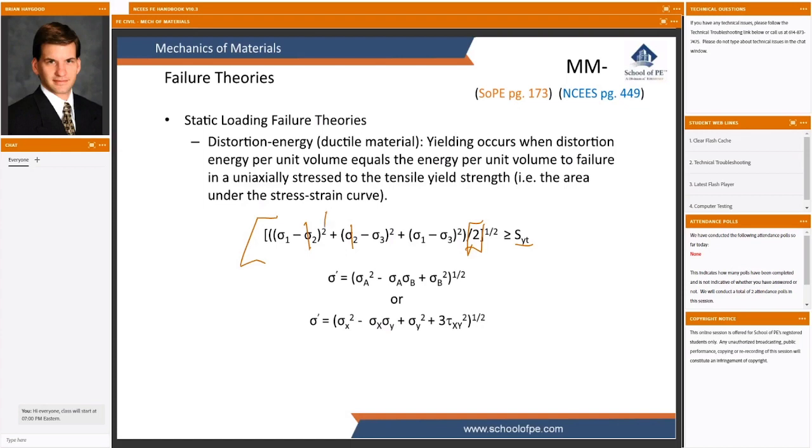So we're going to square these values, square these values, square these values, add them all up and take a square root, which means it doesn't really matter if something has a positive value or a negative value, except that you're comparing them here, so you do have to be a little careful with that. So this is one case in which we use a Pythagorean theorem, but we can't totally ignore the sign on everything. As usual, tension is positive, compression is negative, and as long as you're using that sign convention, this will work out fine.